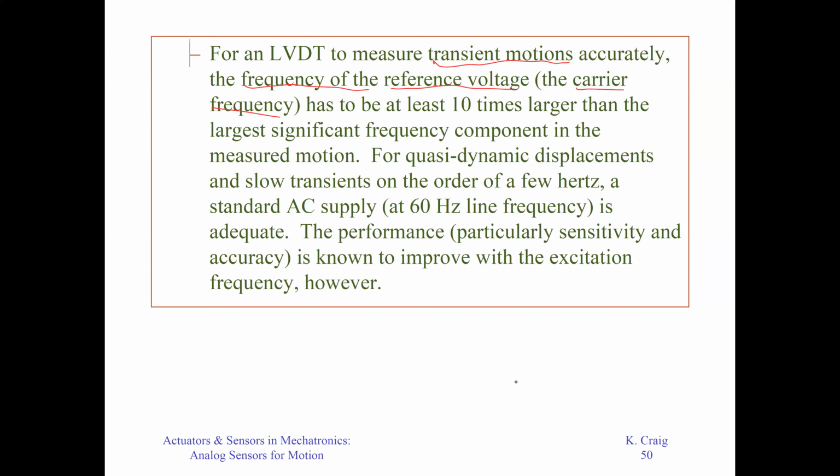It will be 10 times larger than the largest significant frequency in the measured motion. In other words, if you buy an LVDT, there must be a parameter called carrier frequency. The higher the frequency, the more expensive.